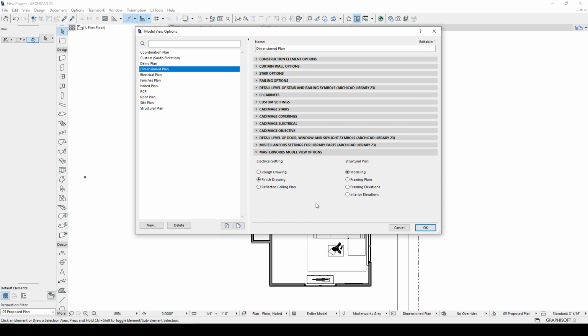Lastly, I have created a GDL object that creates model view options, and here are the two options I have right now. So some of my objects read these and then behave differently based on the setting. This one's used for some can lights, for instance. This one's used for the beam tool, how it models. And so it's looking to these parameters to decide how to display.